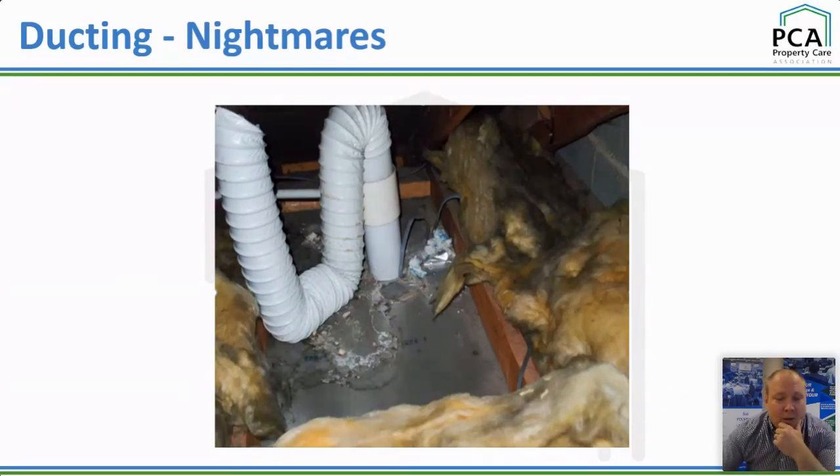But this one, a big thanks, I think this has come from Russell Rafton of DryFix. Thank you for that. But you can see peaks, troughs, elbows, bends. All of those bends are going to be reducing the airflow. And you've got the vertical drops there, which are just going to be ideal for any condensation occurring within that ducting. It is obviously going to come straight back down, and you can see the water staining on the plasterboard ceiling there as well.